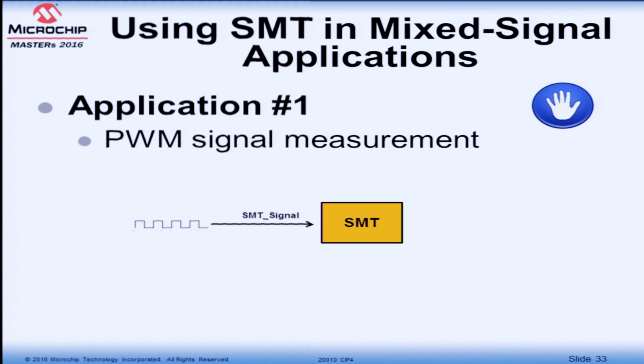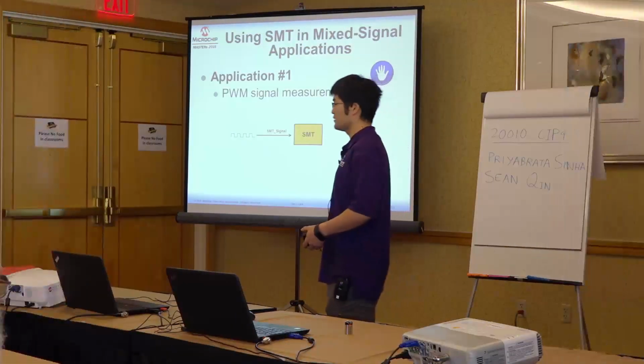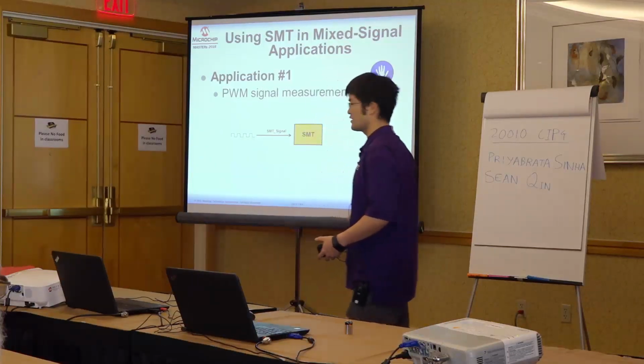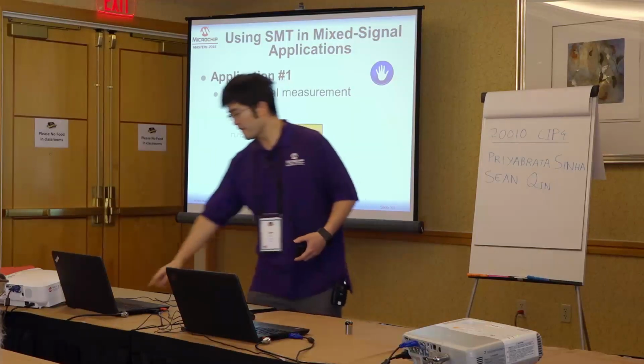All right, so the first natural inspiration for using the SMT is, of course, that I can measure my PWM signals. So I feed my PWM signal into my SMT, and then I can read out the counters for my duty cycle and my period, which is trivial.